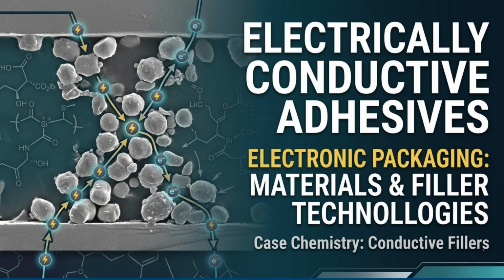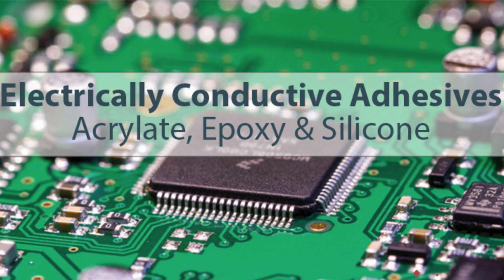ECAs are composite materials composed of two main components: an insulating polymeric adhesive matrix, which provides mechanical strength and adhesion, and conductive fillers, which establish electrical pathways within the adhesive. Common polymer matrices used in ECAs include epoxy resins, silicone, phenolic resins, polyurethane, and polyimides. Conductive fillers may consist of metals such as aluminium, copper, nickel, gold, silver, tin, and zinc, or composite fillers such as Sn bicoated copper particles.